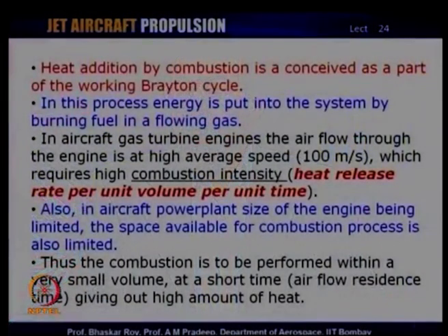In an aircraft power plant, as I mentioned, the size is limited and you have to create your combustion within that limited size. That size limitation puts a restriction on the volume that is available for combustion purpose and the time that is allotted, because the air is flowing at a very fast pace and the residence time of the air inside the combustion chamber is a very small fraction of a second. So, within that small fraction of a second, a very large amount of heat would need to be released inside the combustion chamber, and that is the mechanism which we will look at in today's lecture.